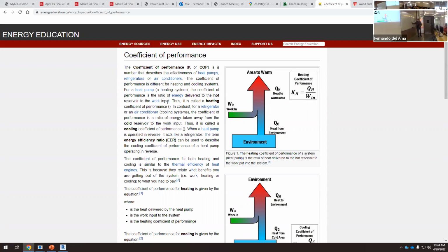If we are working with water-to-water heat pumps, the coefficient of performance can be up to 5 to 7, depending on the outdoor-indoor conditions. So that means that if we want to produce 2 kilowatt hours, and the coefficient of performance is 5, what is the electric consumption?